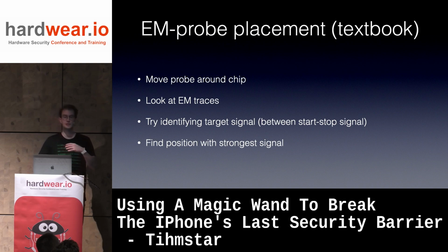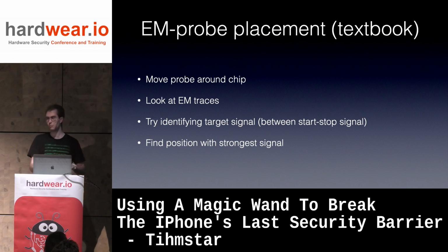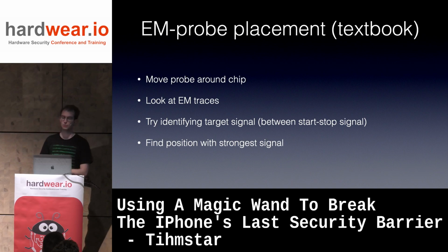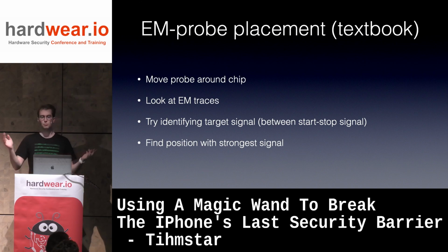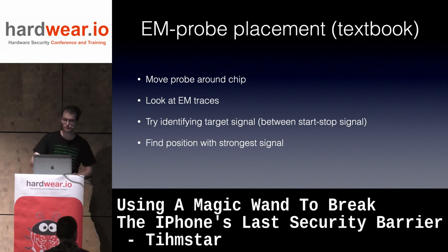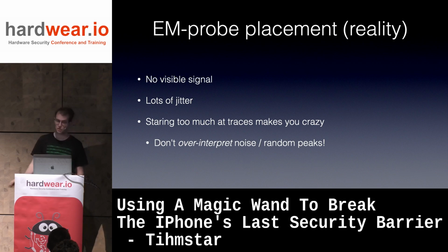Now I actually want to go a step back. Where do you put your probe, right? Because I put the probe somewhere, obviously, but where should you actually put the probe? Well, I had a lecture at university, which tells me, so you take the probe, you move it around, you look at the EM traces, and try to identify the signal. Find just a spot with the strongest signal. Easy enough, right? Well, the reality is much different.